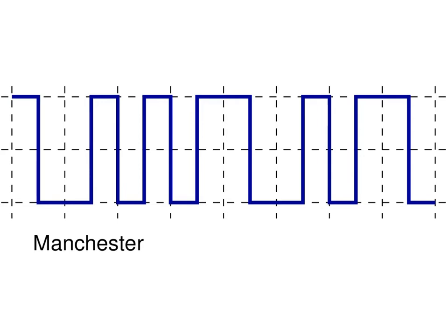If we use Manchester encoding, what's the data if we receive this signal? What's the first bit? So again, we need to know the definition. Bit 0, we make a transition from high to low.